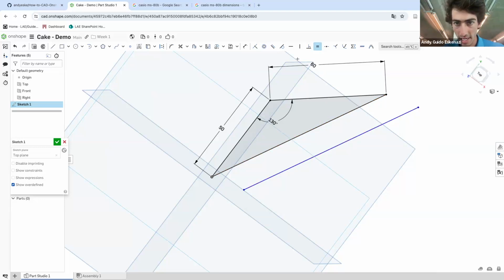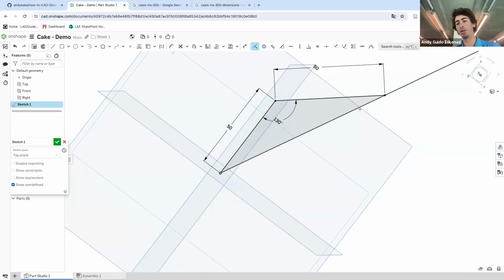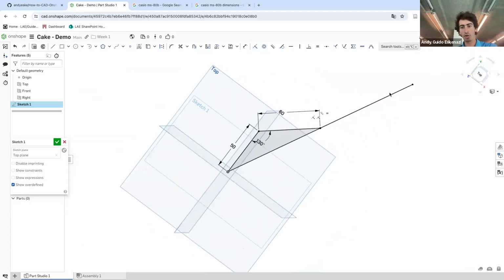And then what else can I do? I can click on I again for coincident and make these two points coincident. So you see, after defining all of the constraints, I didn't provide any dimension. I'm just constraining all of these things in space. So you have that line in there. Hopefully as we do more stuff, all of this will come more naturally.